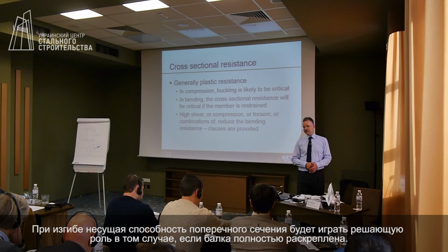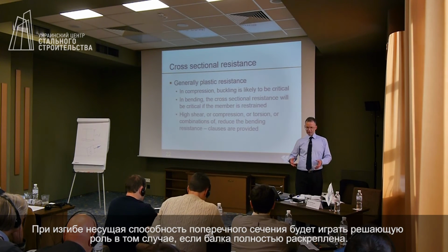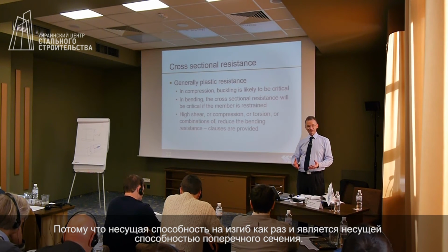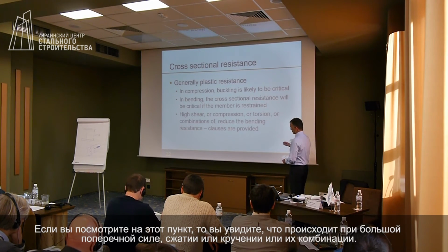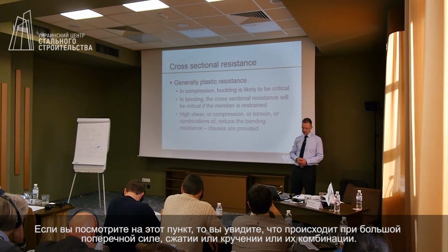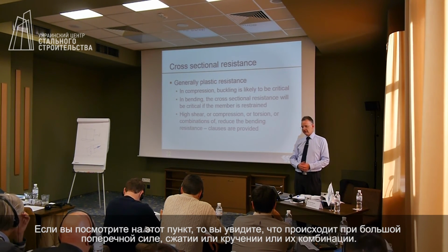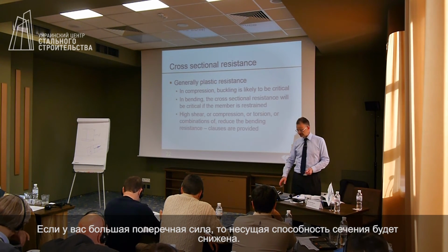We are very interested in cross-sectional resistance in bending if the beam is fully restrained, because then the bending resistance is the cross-sectional resistance. When you look through the clauses, you will find expressions that cover the case when you have high shear, because if you have high shear, you cannot enjoy the full moment resistance.